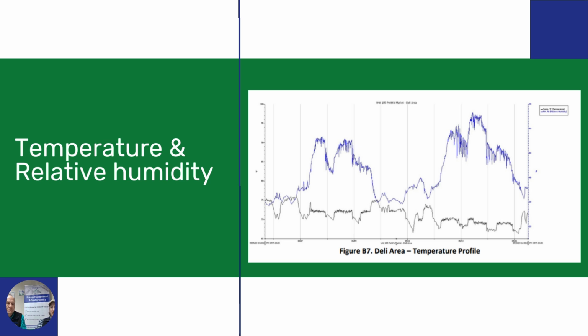And then we go beyond just a utility graph month over month, trying to correlate it to weather. Now we start looking at the different days that we put a data logger in place, and we start looking at the relative humidity compared to temperature. This one has a little bit of fluctuation day over day, hour over hour, but there are big fluctuations here in relative humidity. Those could be time periods in which the building was occupied versus unoccupied.